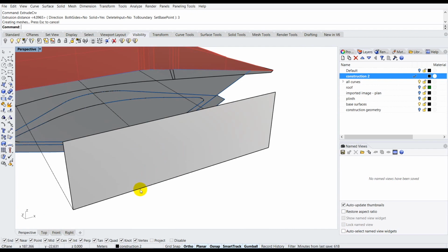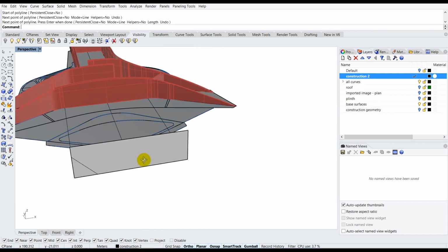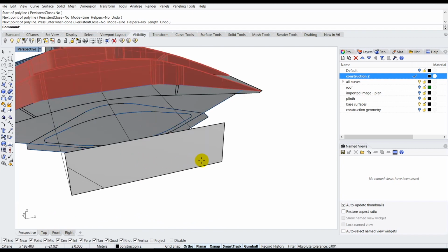So let's try creating a curtain wall geometry on this particular surface. So according to the picture, the geometry goes something like this. So we'll try creating that. So you can actually select a point over here. The random point you can select over here. You can actually snap the point somewhere over here, and we can try the same thing on this particular end.